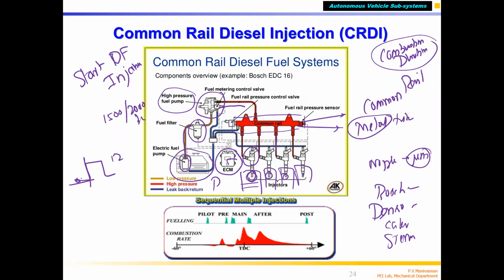Just like in a petrol engine, the piston is moving up. When the piston comes to TDC, as a thumb rule, at least 50% of the fuel should have been burned. Only then will the maximum pressure be created inside the combustion chamber. The hot gas will push the piston down with a force, which is converted to torque in the crank mechanism. You get maximum torque. We know that both petrol and diesel engines are torque machines.